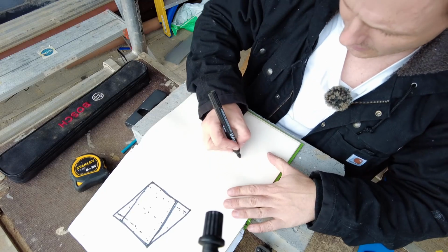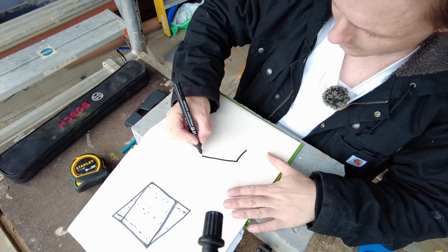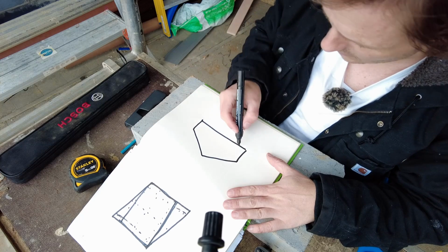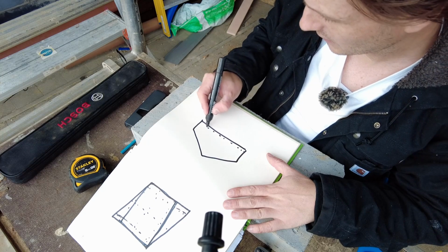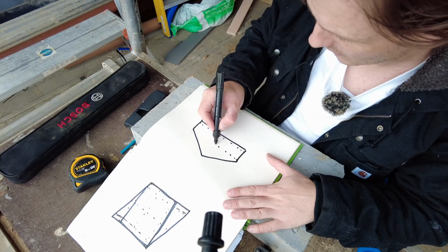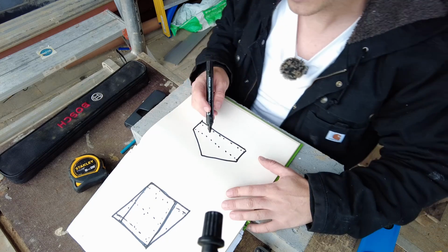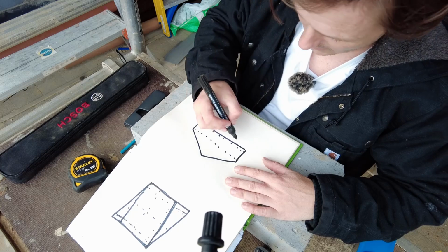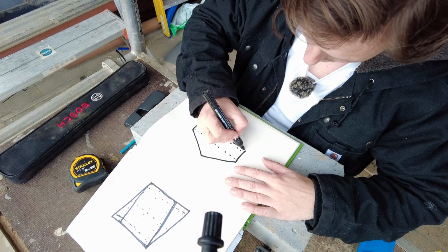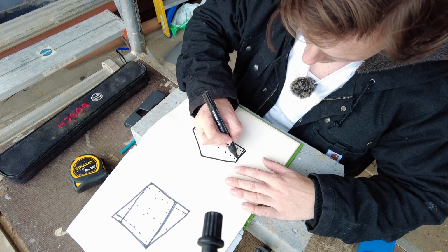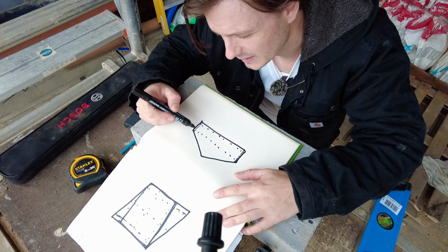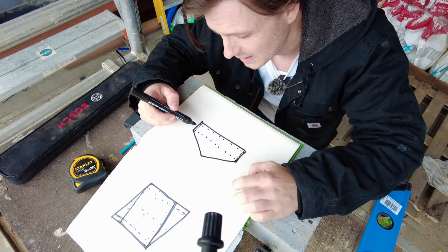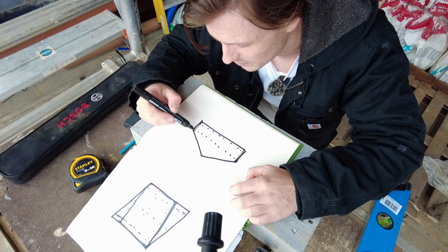Principle of this, I've got 2 upstands either side. So I want to measure 1 across here, 1 across here. I'm going to take that smallest measurement and deduct 15mm again. Then what we're going to do is we're going to measure here. So just remember that these measurements at the very end, they're going to be slightly different if you drop them in. So be careful on what you're measuring.